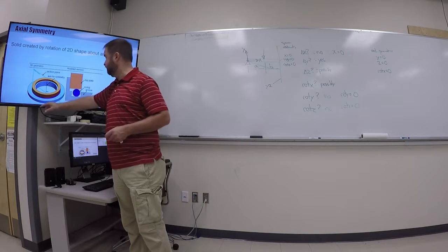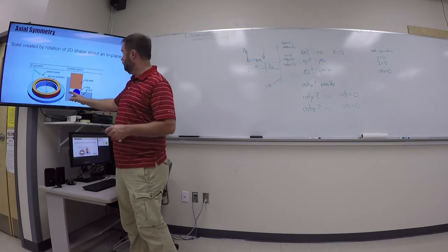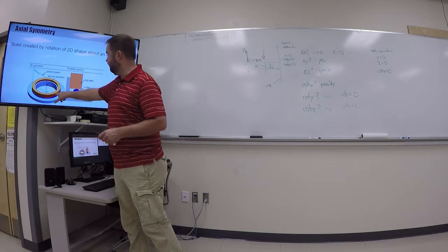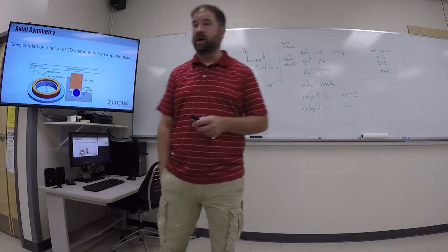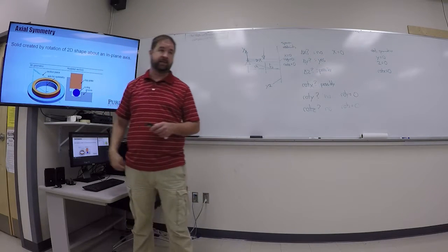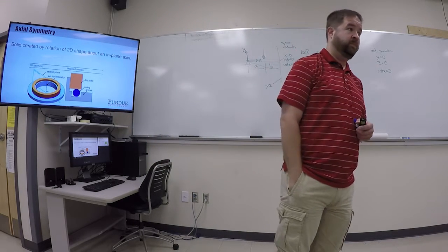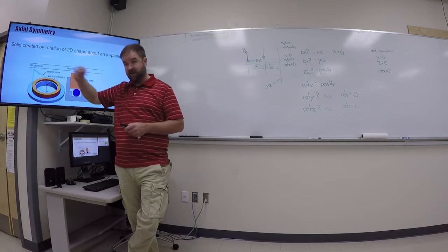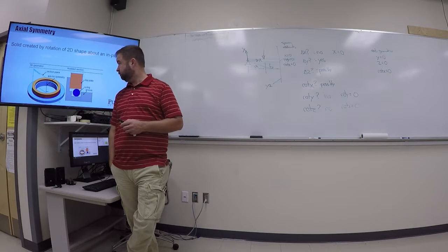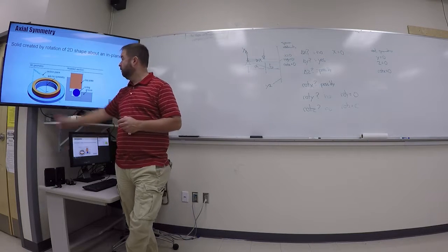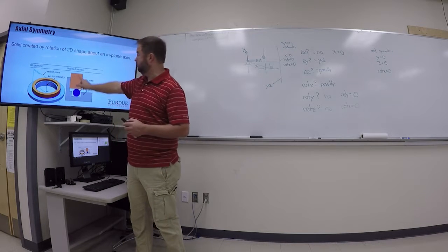So this particular example is a case where we have an O-ring that is in blue here. The O-ring is in a slot, and then we have something that is compressing the O-ring, and we want to do a model of that. This has axial symmetry in that if I take a section anywhere along that, the geometry is exactly going to be the same. If I model this in 3 dimensions, this is going to be a huge number of nodes and elements because of having to do all of the solid elements around that whole thing. It's going to take a relatively large amount of time to analyze that. But using axial symmetry, I can reduce all of that down to just the cross section.